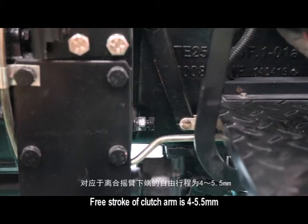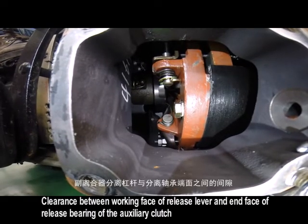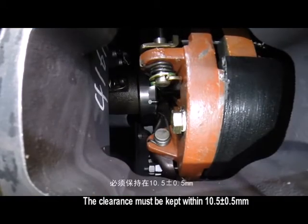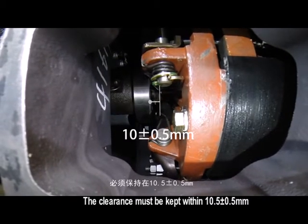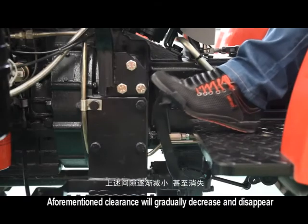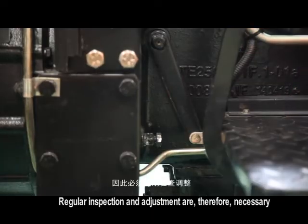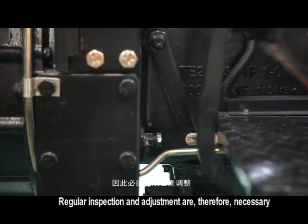Free stroke of the clutch arm is 4 to 5.5 mm. The clearance between the working face of the release lever and the face of the release bearing of the auxiliary clutch must be kept within 10.5 ± 0.5 mm. During operation, due to continuous abrasion of the clutch friction plate, the aforementioned clearance will gradually decrease and disappear. Regular inspection and adjustment are, therefore, necessary.